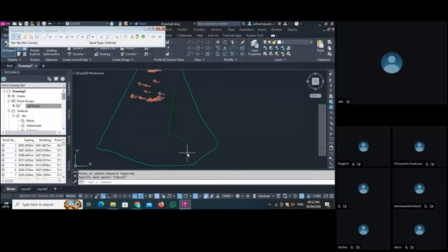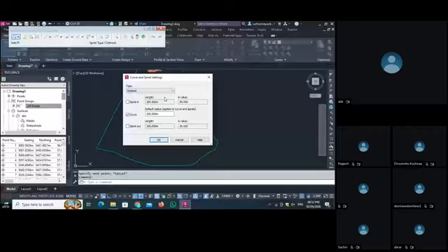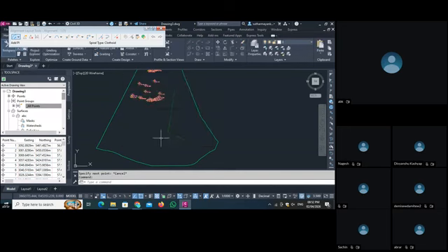If you want to provide a curve, then you must select the tangent with curve. If you have some setting, like I want to take this length and I want this type of radius in my alignment, you can choose any method from here and set your code and set okay. Then whatever you use, as I set this criteria first, all my work is based on that criteria only.